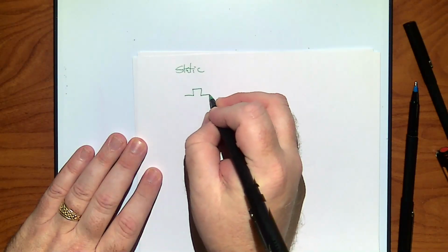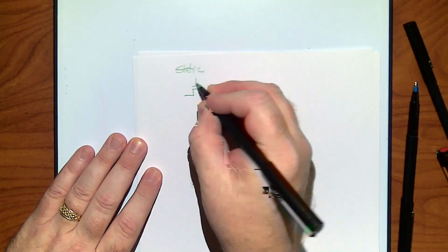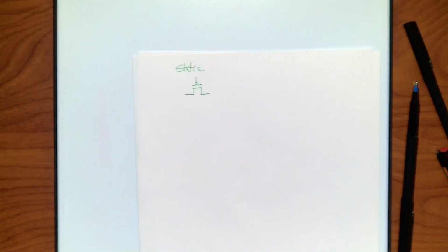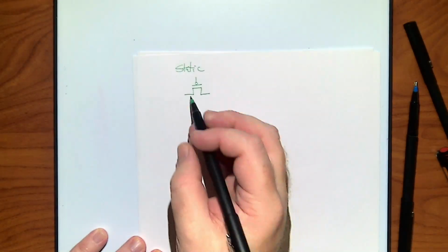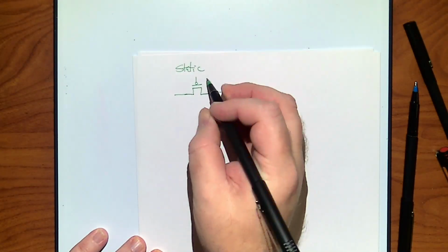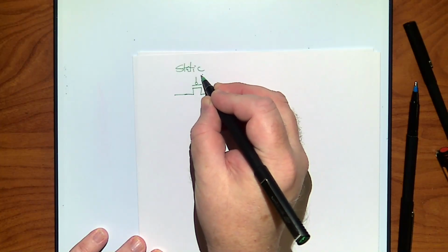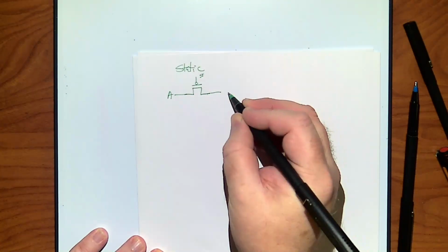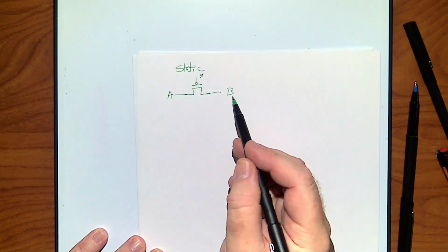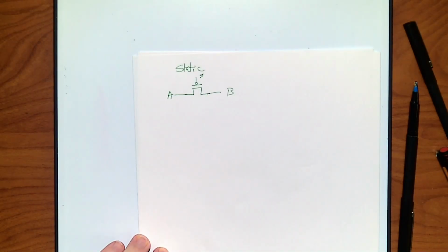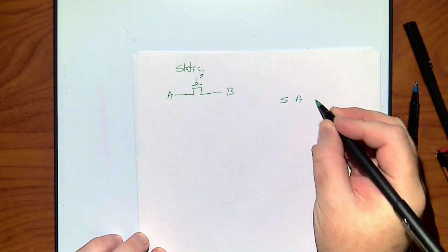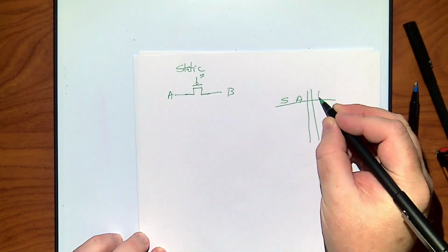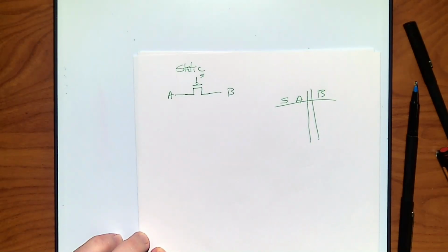We've talked about this a little bit: if I had a PMOS gate like this, let me call this S here, and here's A, and here's B. I'm going to consider A my input and B my output, so I twist the gates so that's the natural direction. So S and A are inputs, and B is an output.